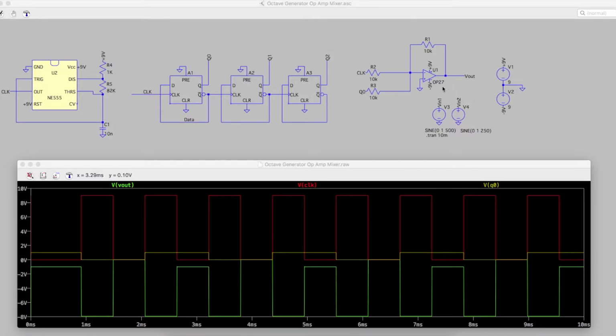Over here for the op-amp, I'm going to be changing this from a dual plus and minus 9-volt split supply into a single 9-volt. So I'll put a voltage divider on this non-inverting input, and all these 10K resistors are probably going to get changed based on what I have available and what I need to do to the signals to get them to work out in my setup.